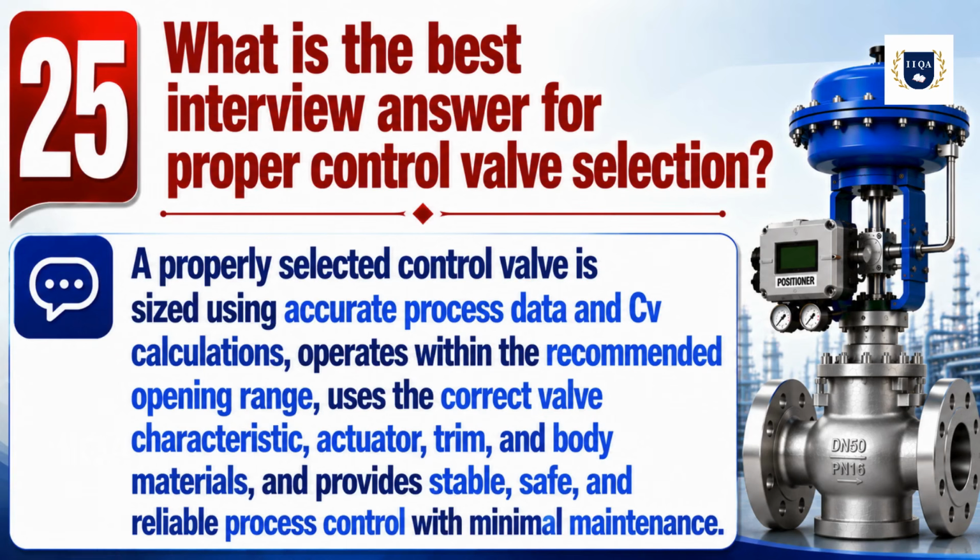25. What is the best interview answer for proper control valve selection? A properly selected control valve is sized using accurate process data and CV calculations, operates within the recommended opening range, uses the correct valve characteristic, actuator, trim, and body materials, and provides stable, safe, and reliable process control with minimal maintenance.